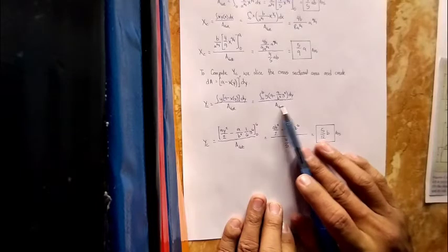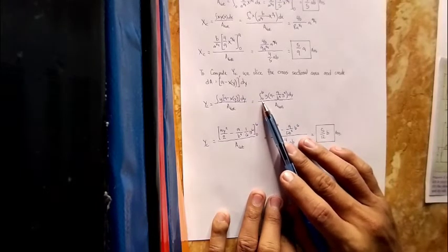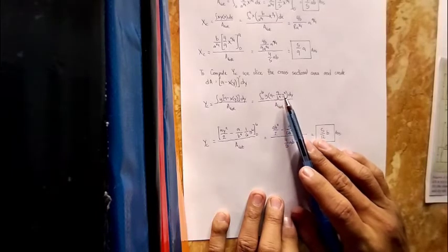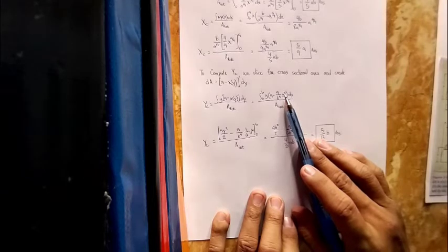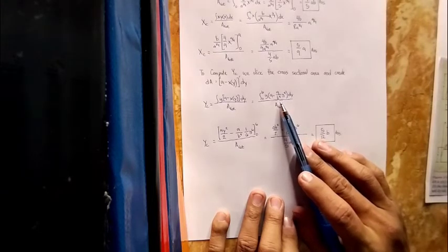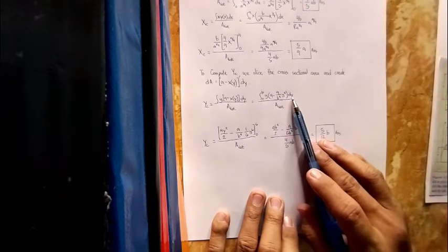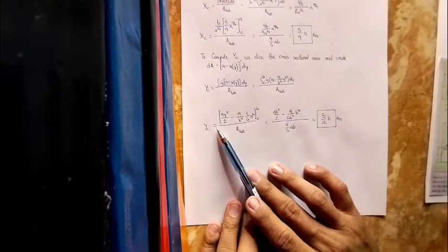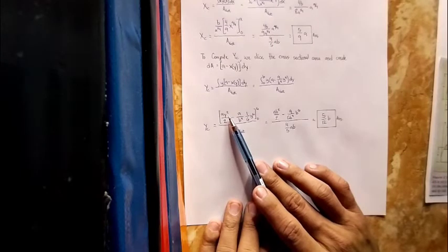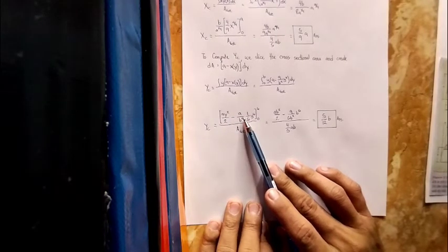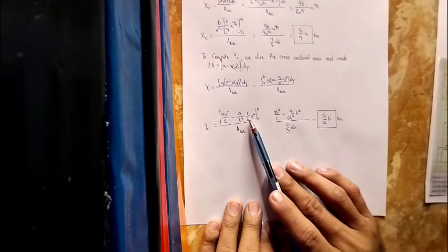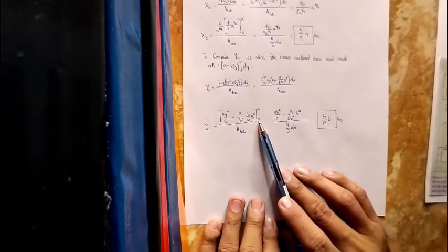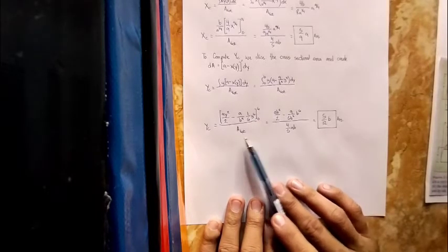We substitute the values. It equals to integral of y times the quantity of A minus A over B raised to 4 times y raised to 4 dy over the total area. Centroid of y is equals to A times y raised to 2 over 2 minus A over B raised to 4 times 1 over 6 times y raised to 6 with the interval of 0 to B over total area.